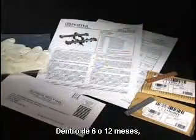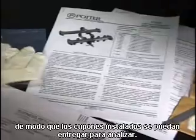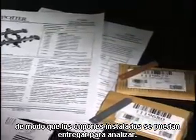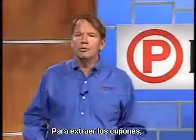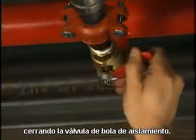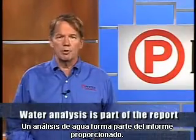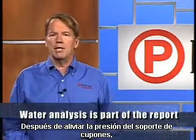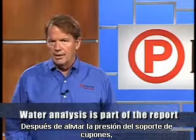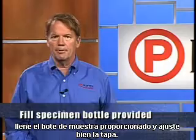After 6 or 12 months, you will need to order a Potter coupon replacement kit, so the existing coupons can be sent in for analysis. To remove the coupon rack, it can be isolated from the system by closing the isolation ball valves. Water analysis is part of the report provided. After the pressure is relieved from the coupon rack, fill the specimen bottle provided and securely affix the cap.